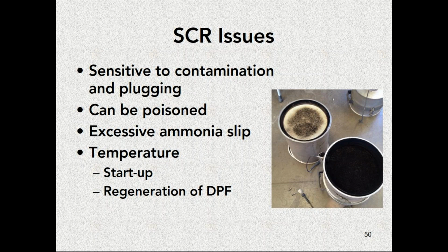So when the temperature is not high enough or too high, it actually causes something called ammonia slip, and that is where the ammonia does not get consumed in the SCR catalyst reaction, and it's able just to go straight through and out the exhaust. Oftentimes you'll know this is happening because you will smell a really stinky ammonia type smell around some vehicles that are having some problems.